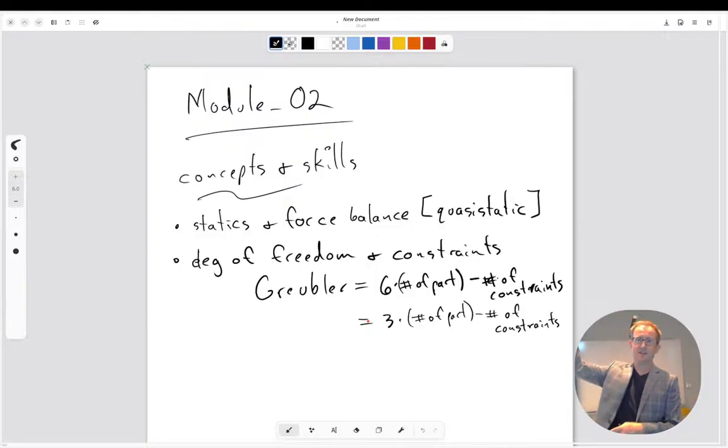If you put a hinge on the top of the door and the bottom of the door, according to math, 6 minus 5 minus 5 is now -4. But the second hinge is the same constraints as the first hinge. So negative Grubler count usually means you're creating the same constraints more than once. Here, we don't have to deal with it too much.